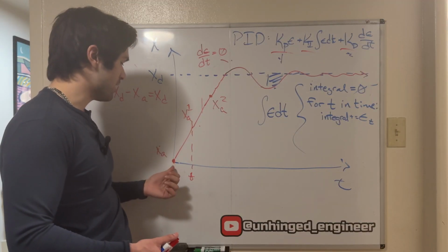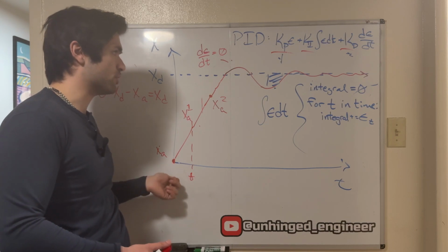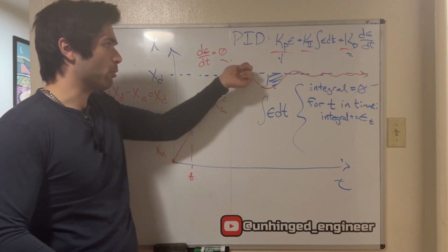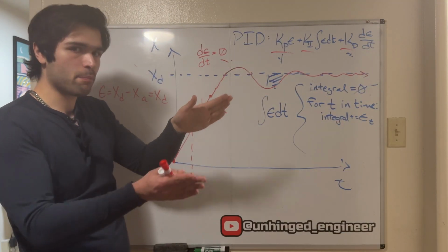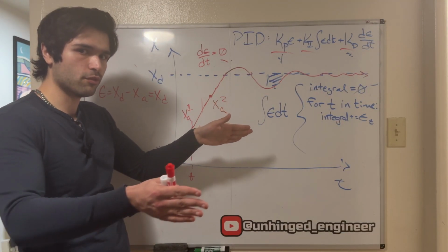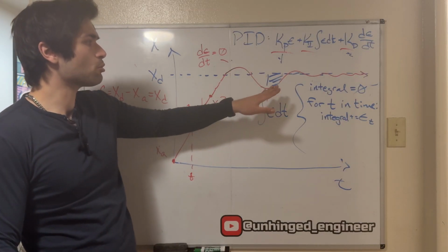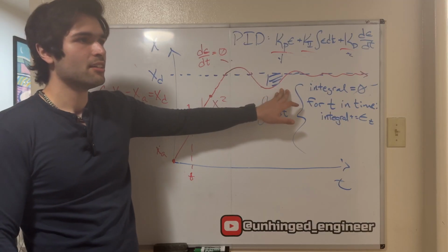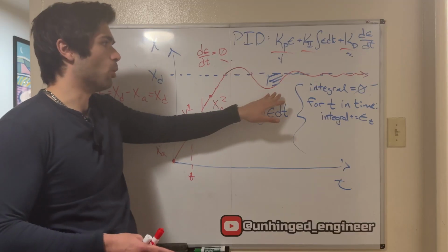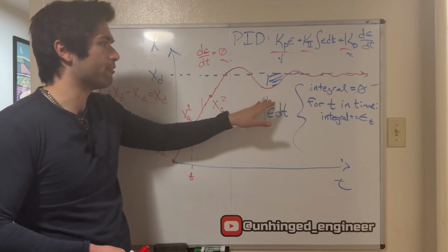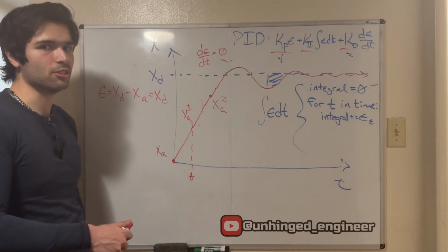We have the proportional term that's driving our error towards 0, so it's forcing our system to go towards the set point. At that point, it's going to oscillate about it. And so the derivative dampens those oscillations over time. So it scrunches things down and makes it converge on the set point. And then the integral makes sure any bias in how our model is different from the actual real system is ultimately factored out, and you really can be confident that you're converging on the set point you set in the very beginning, which is ultimately what we're trying to do with the control system.